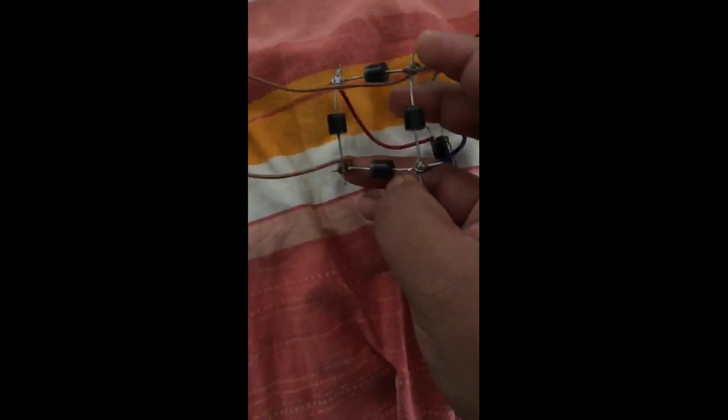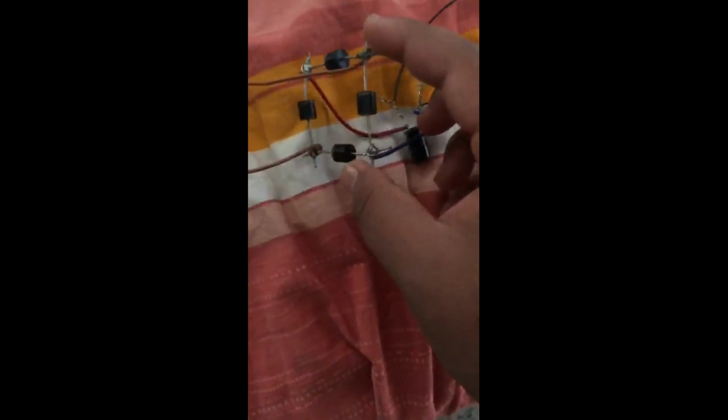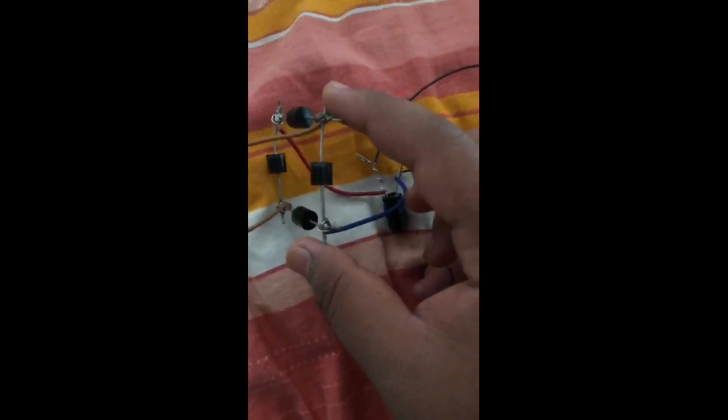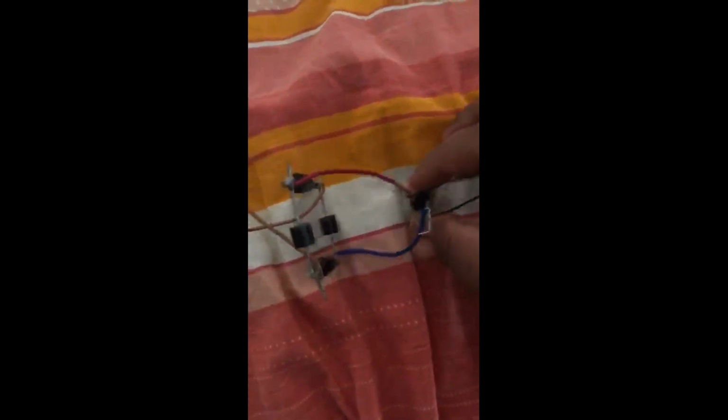and this is a full wave bridge rectifier. This converts the AC voltage into DC voltage, and further this is a capacitor. So this circuit is a setting which converts AC voltage into DC voltage, and we lack a multimeter, but if we had a multimeter we could show that there's a stable 12 volt DC current generated.